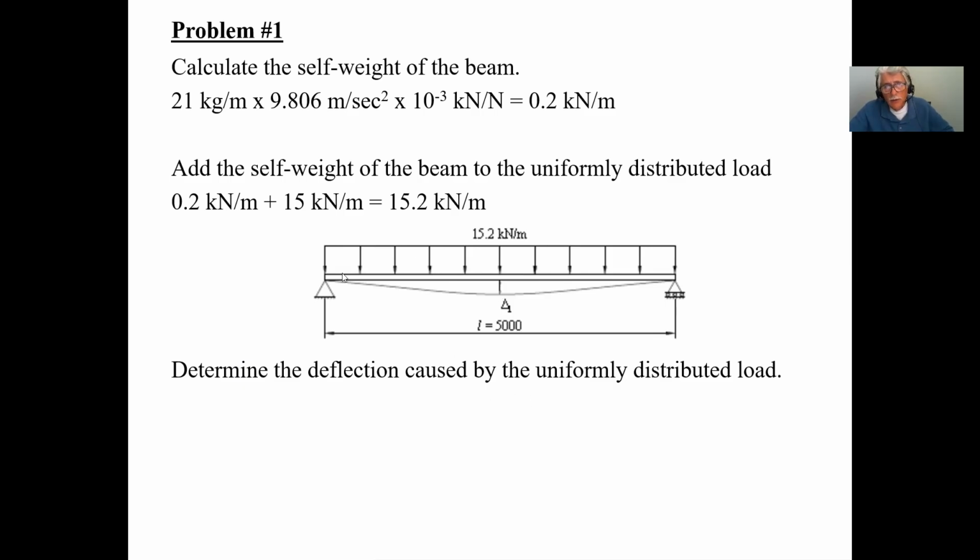The best thing to do here is look at my diagram. When you're looking at these diagrams, if you want to use the beam formulas, you have to look at your supports and you have to look at the loading, okay? If you have the same supports and you have the same loading, then you can use the beam diagrams, all the formulas that correspond to that diagram you see in the beam formulas, okay? So that's what you have to worry about.